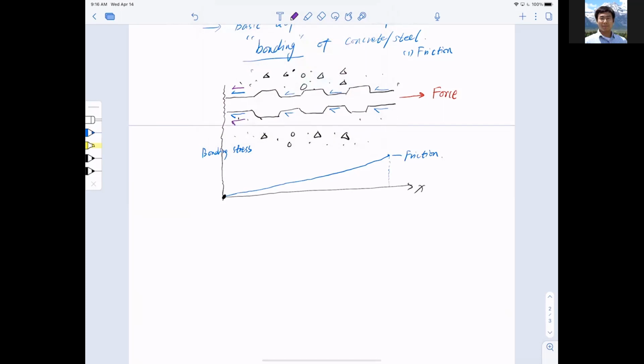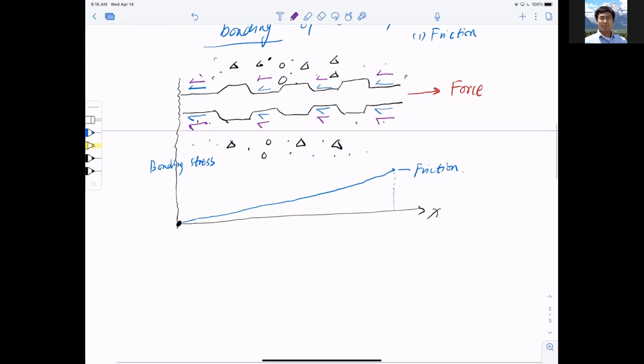Meaning the components of the concrete will react slightly with the surface of the steel or rust layer to create a chemical bond. And you realize that this chemical bonding also predominantly exists at the flat region of the bar. So this also contributes to the bonding stress. That means my concrete is trying to grab on the rebar. When the bar is trying to pull away from the concrete, not only do I have abrasion or friction, I also have adhesion, something quite sticky there.